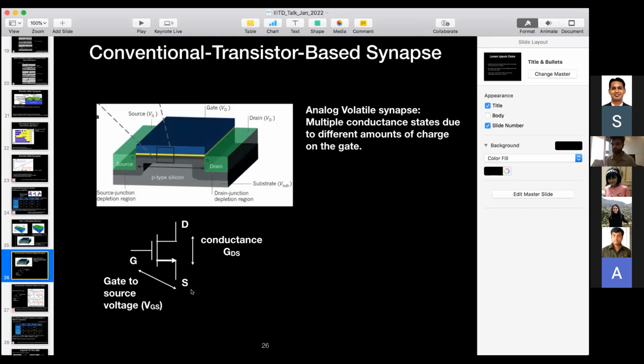So just like in the Spintronic device, a three-terminal device where current pulses to the third terminal change the conductance between the other two terminals, here also current pulses applied at the gate change the conductance between the drain and the source. This was a device proposed by our research group. And the good thing about this device is it is much easier to fabricate than a Spintronic device, because this is just a regular MOSFET. We are taking our MOSFETs and running them only in the linear region.